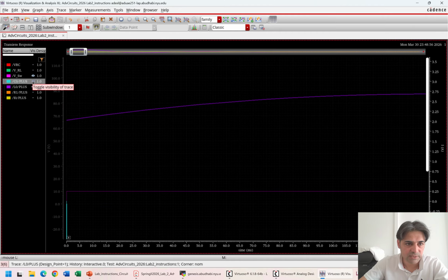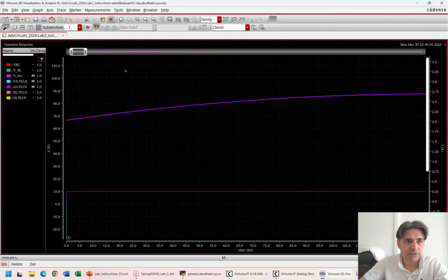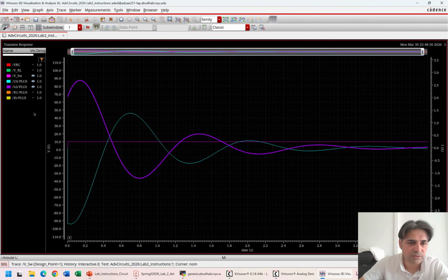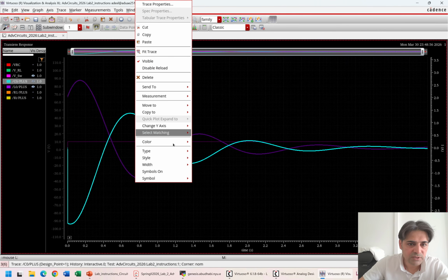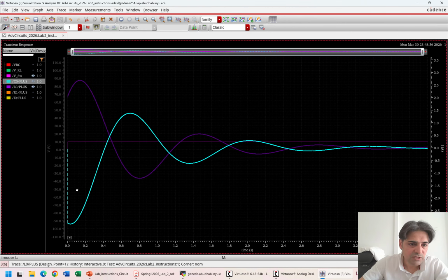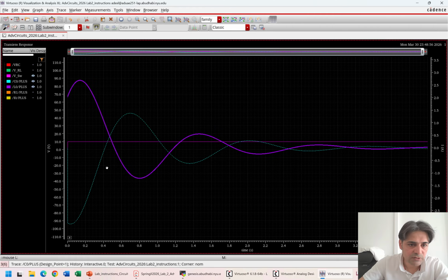For example, looking at this, where is the fit here? This is fitting the window. Now if I want to look at the other plots, please always use different colors, different styles. You can use this one as a dash, this line as a dash dot, all those kinds of things. If you want to put more plots in one figure, do this.